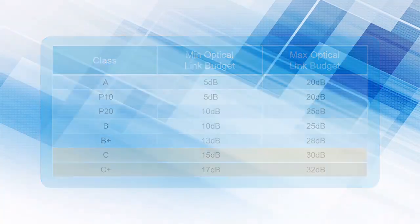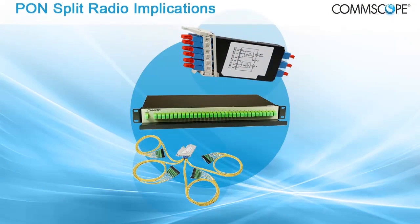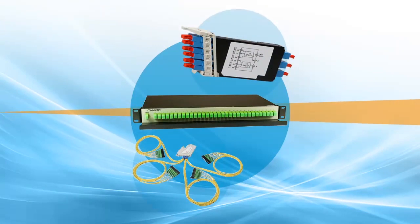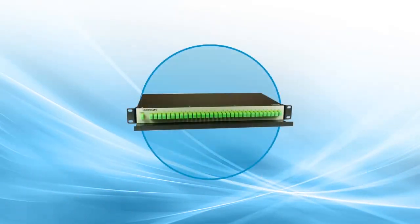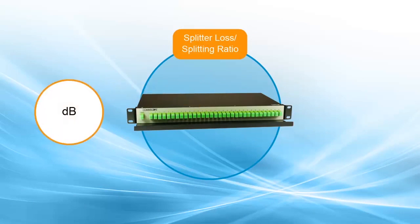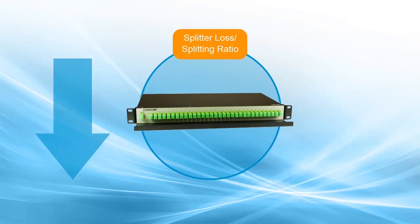Splitters are passive devices because they require no external energy source other than the incident light beam. They are broadband and only add loss, mostly due to the fact that they divide up the input downstream power. This loss, called splitter loss or splitting ratio, is usually expressed in dB and depends mainly on the number of output ports. It should be noted that contrary to what one might expect, the splitter adds approximately the same loss for light traveling in the upstream direction.